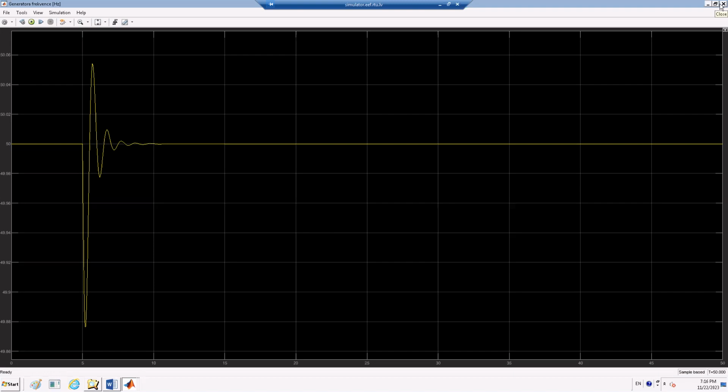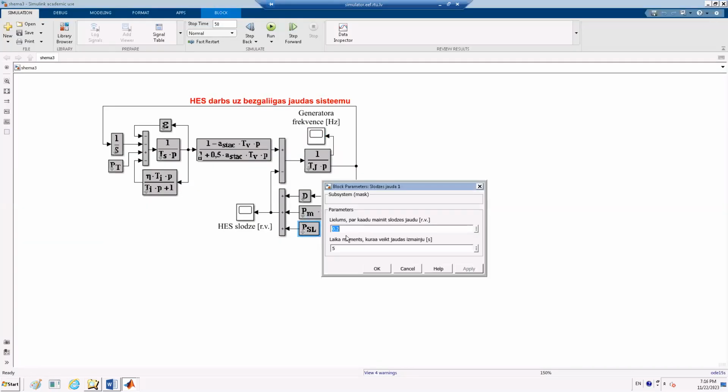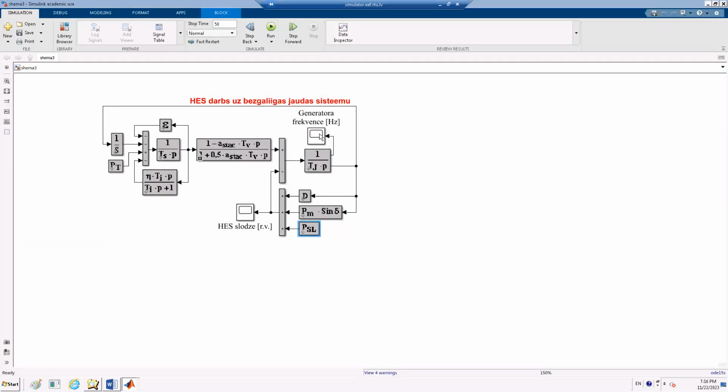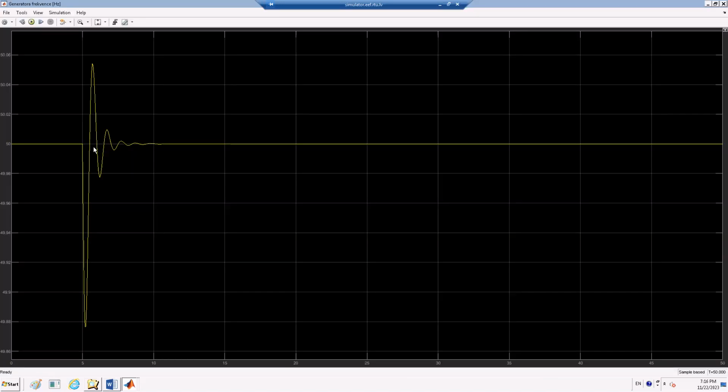And the main interesting thing is the time, because here, in the same scenario, at the time of 5 seconds, we have a deficit. Okay, let's see what is the deficit here. Okay, 20%, the same, 20%. And we have a power drop, we have a frequency drop here, we have an operation of the regulator. We could see the overcompensation. Yes, we have an increase of frequency and stabilization.